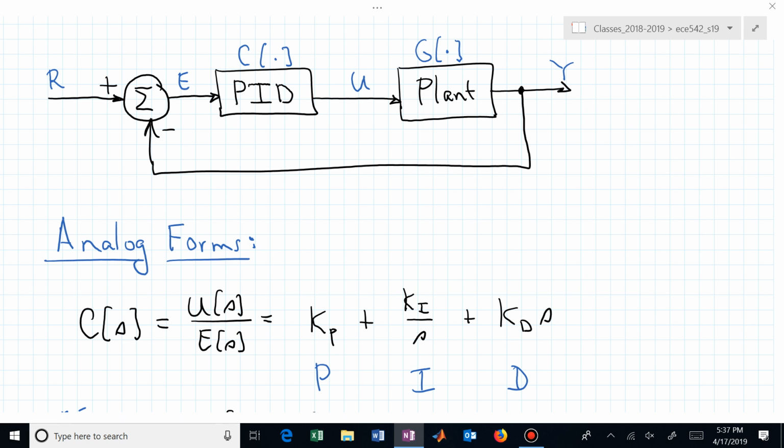If somebody hands you a PID controller, which you can buy off the shelf and plug in, you now have various knobs on the front of that, or access to those gains, and you can adjust or turn those. That's how you can think of weighting the P term.